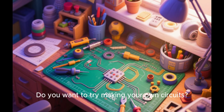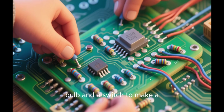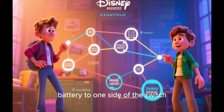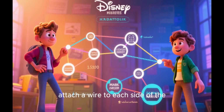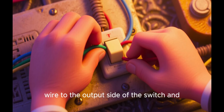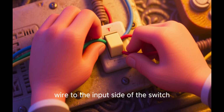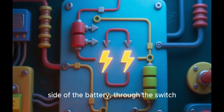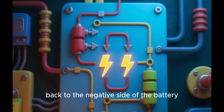Do you want to try making your own circuits? You can use a battery, wires, a light bulb and a switch to make a simple circuit. Connect the positive side of the battery to one side of the switch, connect the negative side of the battery to the other side of the switch and attach a wire to each side of the light bulb. Then connect the positive wire to the output side of the switch and connect the negative wire to the input side of the switch. Now, when you close the switch, electricity will flow from the positive side of the battery, through the switch, through the light bulb and back to the negative side of the battery.